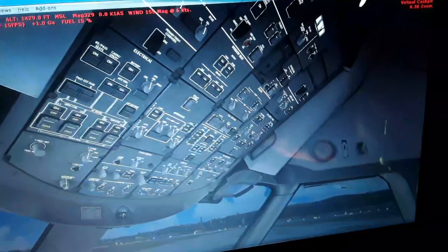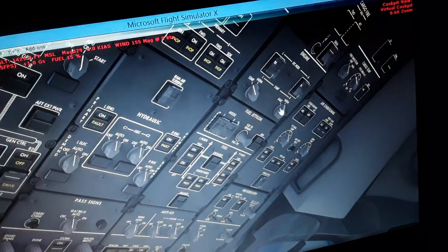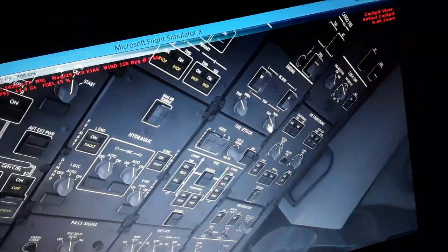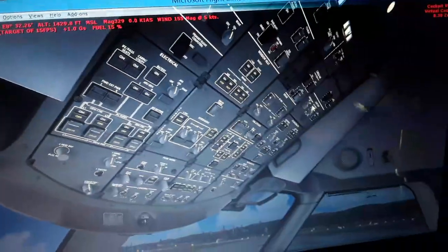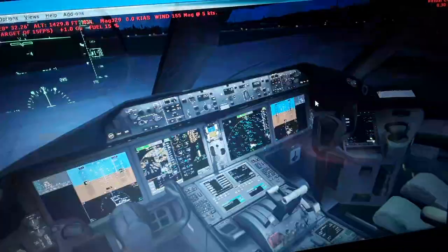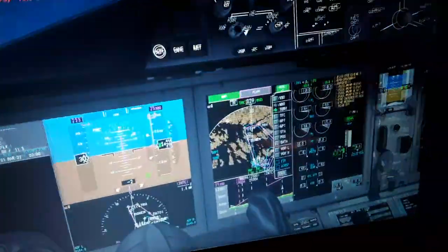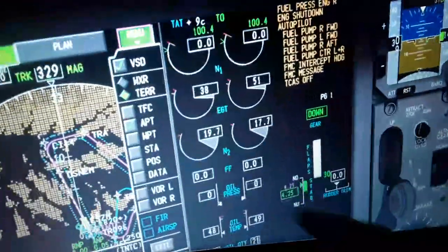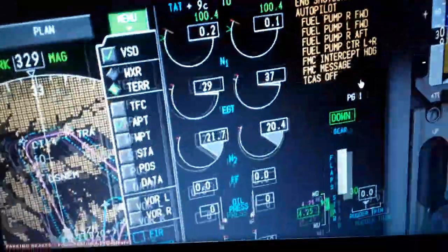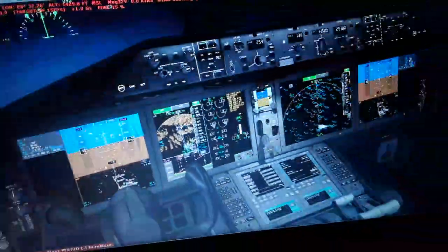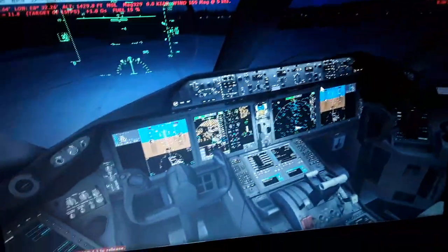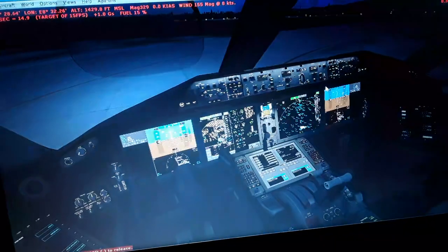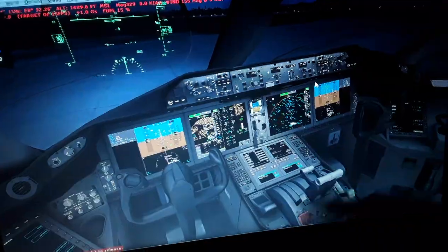So we come over here and turn both left and right engine controllers to the auto. So you see the amber indications are reconfiguring themselves. We have high pressure from the APU right now into the engine compressors, as you can see. Starter. So we need only to start. We have pressurizer. So we need only to start over here the fuel control like this.